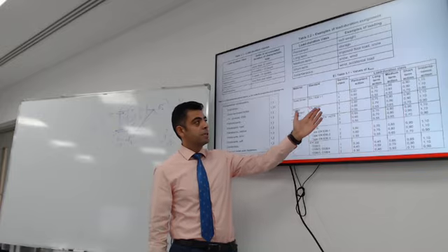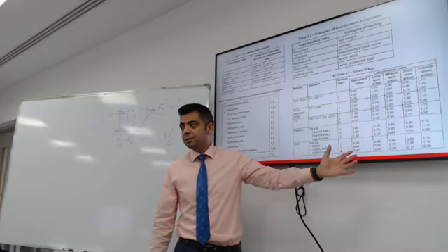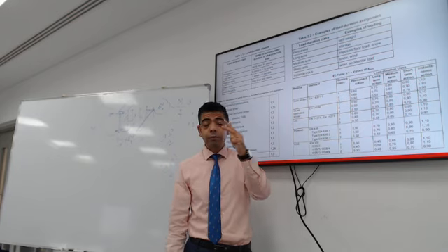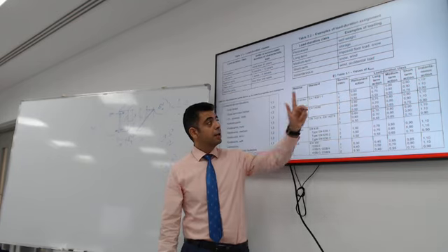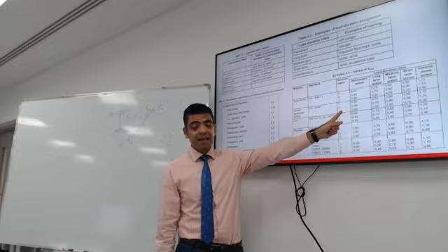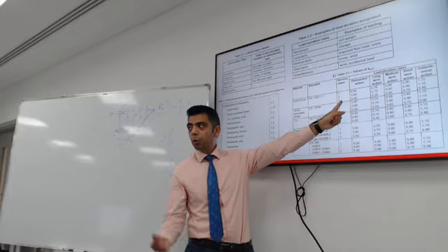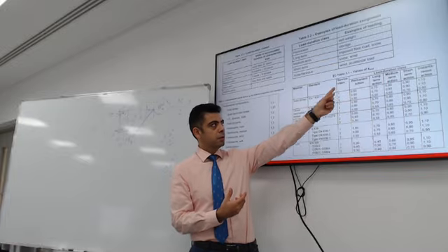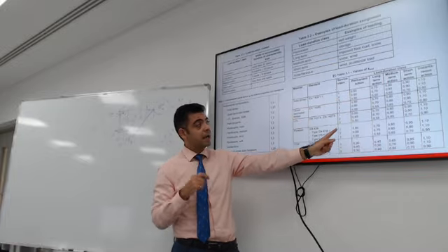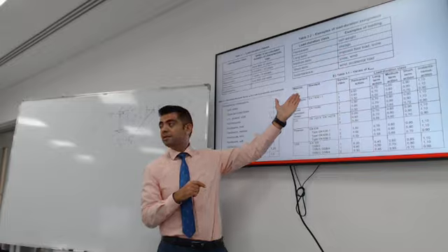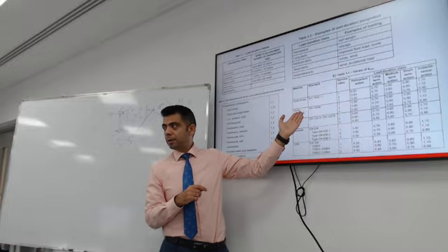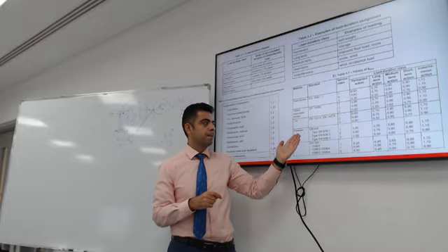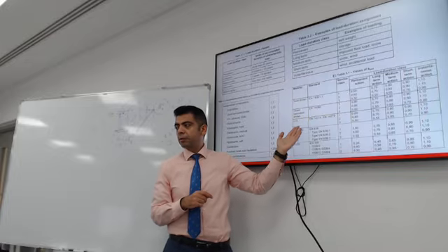All right. So what are all these numbers? There are 3 things into play. There is the service class. Is it fully exposed, class 3, or indoor, class 1, or just a cold roof environment, class 2? So that's the first variable. The second variable is what is the material? Is this solid timber? Is it Glulam? Is it LVL? Is this plywood? And so on and so forth.